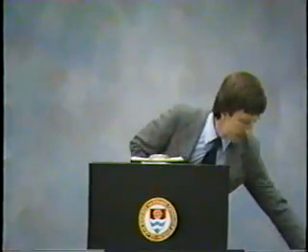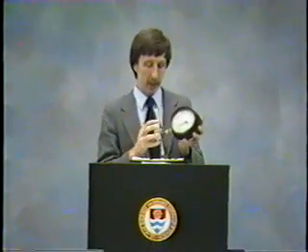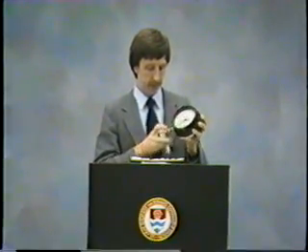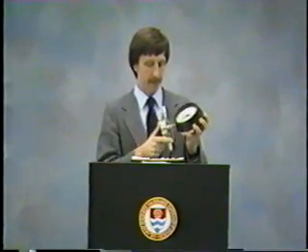So the best thing to do, when you buy this equipment, if they happen to give you some of these inexpensive gauges, is to just get rid of the gauge and go out and buy a good gauge. This is typical of the gauges that we use. They have gradation marks at every psi. They're ANSI type A gauges. With these, you can get some pretty good accurate and precise measurements. All you do is connect this to the hydrant cap fitting. Get it good and tight and attach to the hydrant, and this will give you the kind of results you'd like to get.